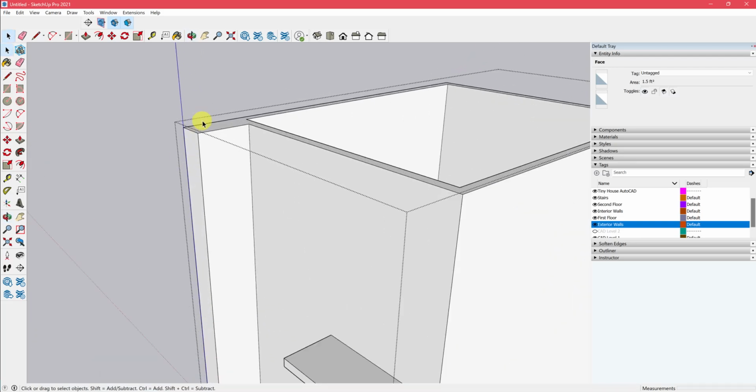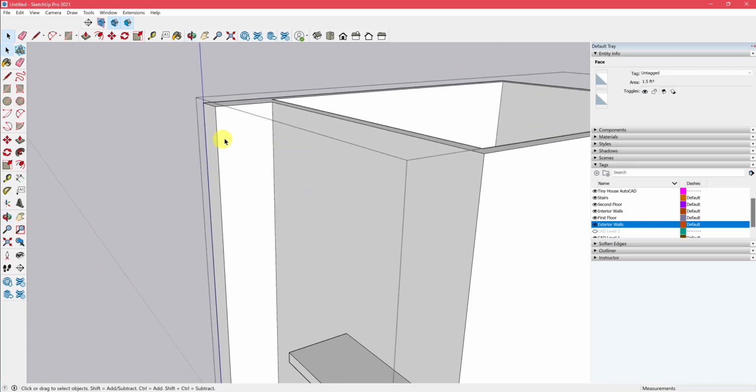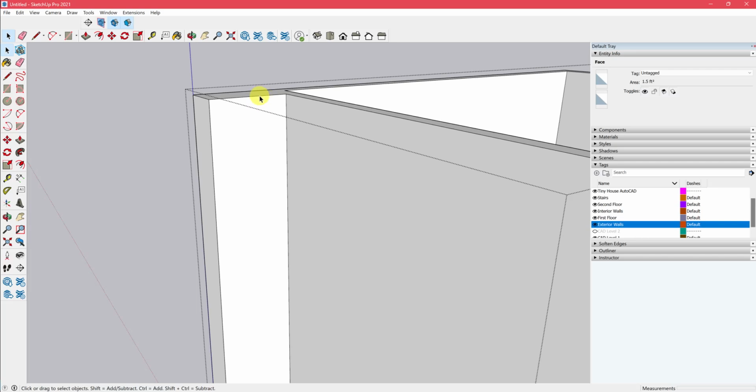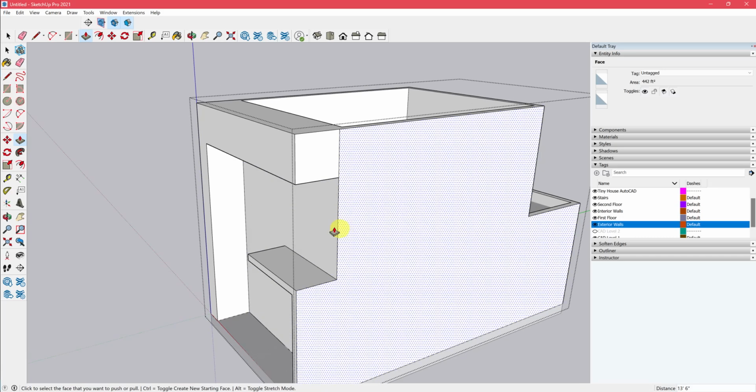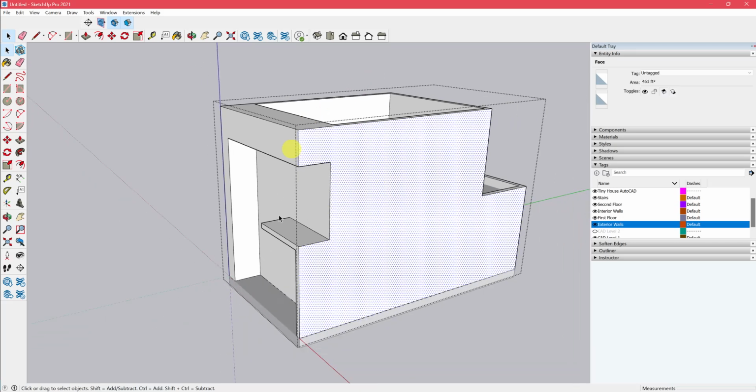So we'll do similar, get to the inside face of this wall, and I'm just going to, oops, M for move, Control for copy, copy that down 3 feet, and extrude this top surface all the way across, aligned to this right edge of the walls. Erase any extra line that was created so we have one nice long surface.